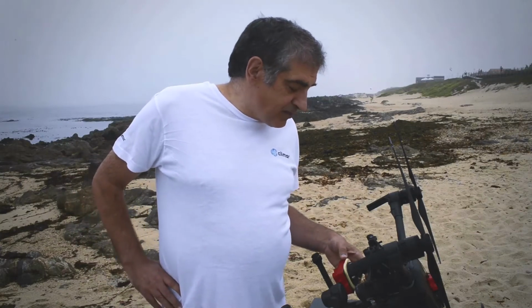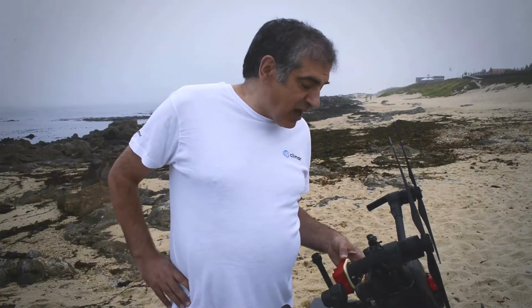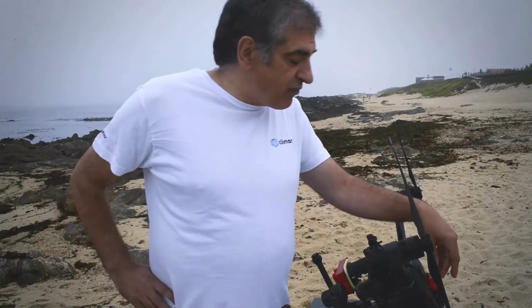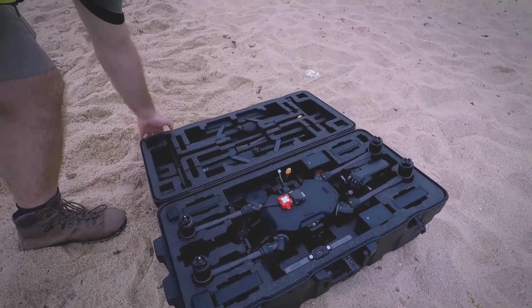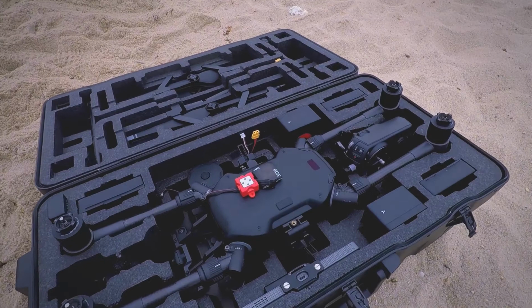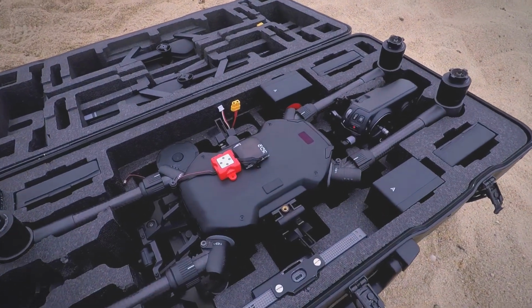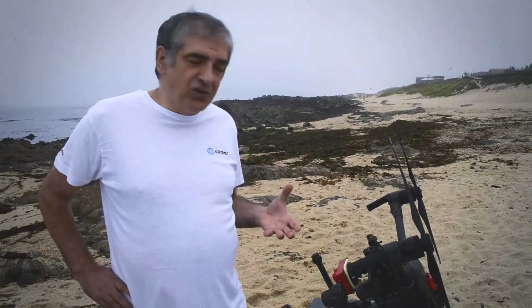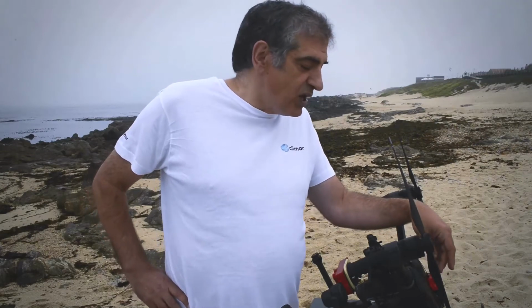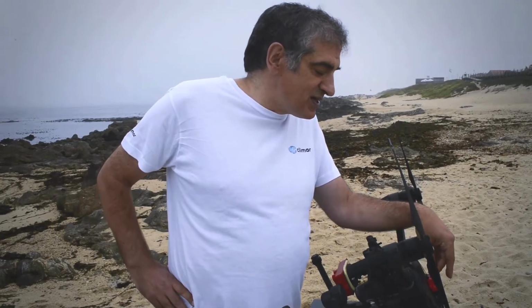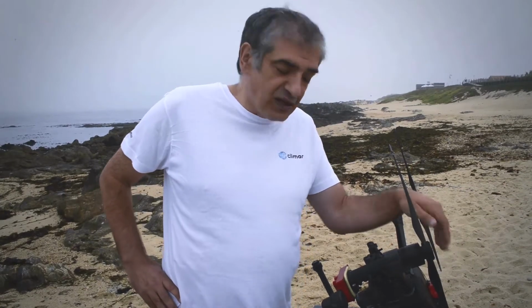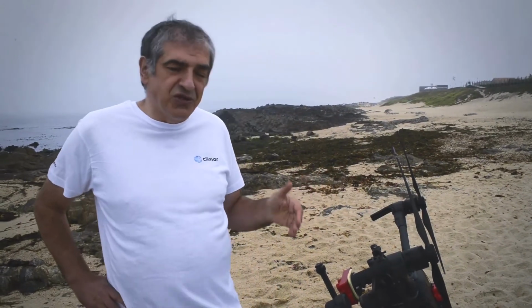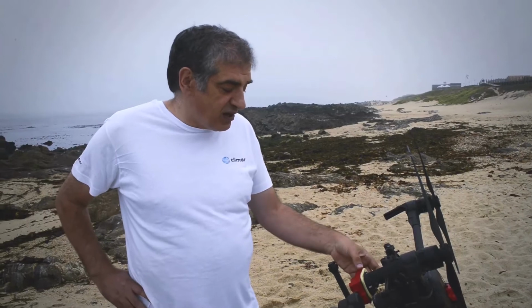For the multispectral camera, we also have here a radiation sensor, because the images that we are getting will capture the radiation that is being reflected from the ground, radiation that comes from the sun. So we need to know what radiation we are getting from the sun at that moment. So there is a sun radiation sensor that is needed to calibrate the images for the moment of the flight.